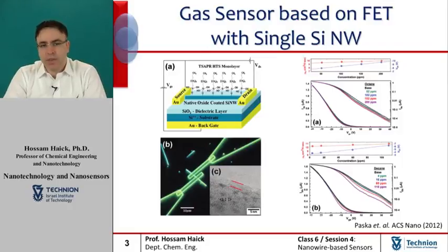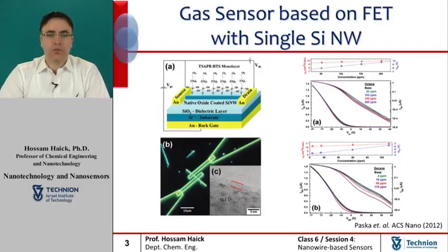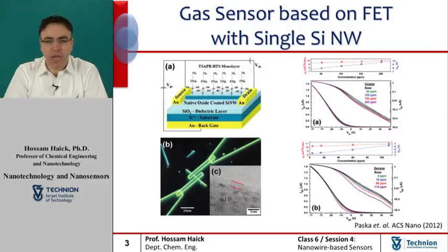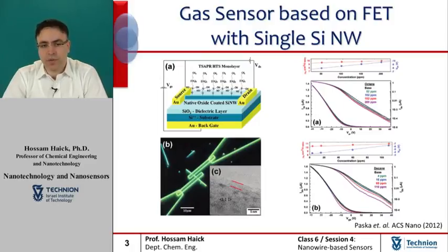In this system, the adsorption of gas analytes, or volatile organic compounds, induces conformational changes in the organic monomer and affects the dielectric constant. In this case, the effective dipole moment of the organic monomer or the charged surface state density of the silicon oxide monomer interface are changed. These effects in turn change the conductivity of the silicon nanowire quite effectively.